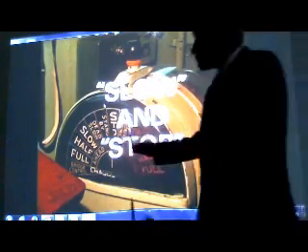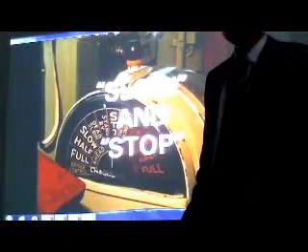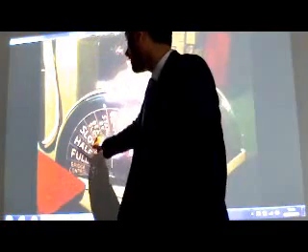What you need to know is maximum of the vessel's maneuvering happens between half to stop. Between your vessel's 50% to 0% of your vessel's engine's performance. If you are going anything beyond that, well, that is either for your longer deep sea passages for a steady direction maintenance, or for otherwise you are just going to be operating for your vessel. When your vessel is operating in and around a port, it will be in this range, maneuvering.